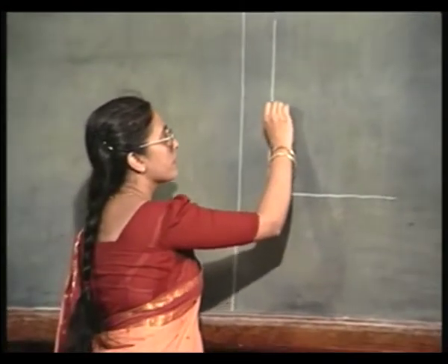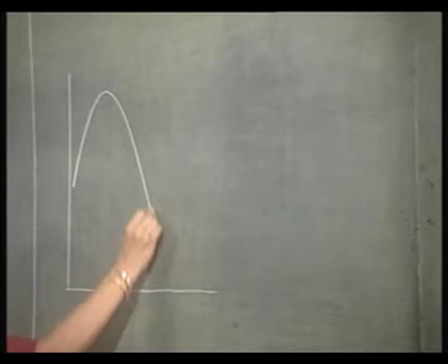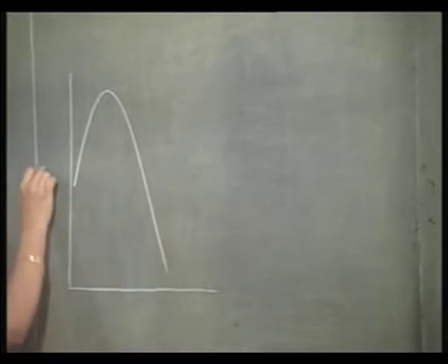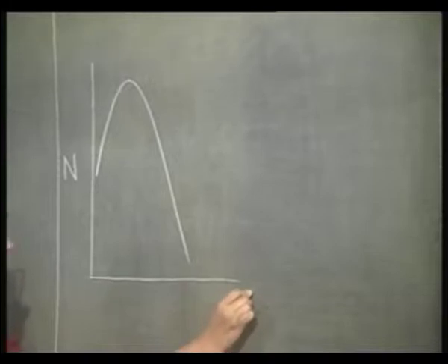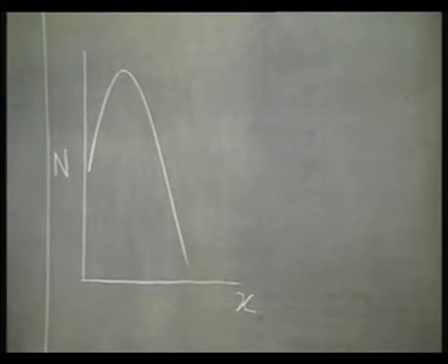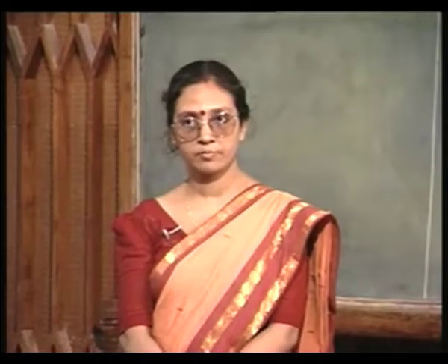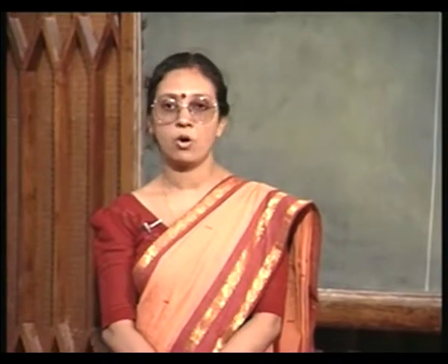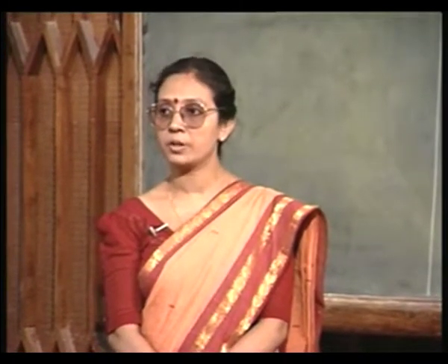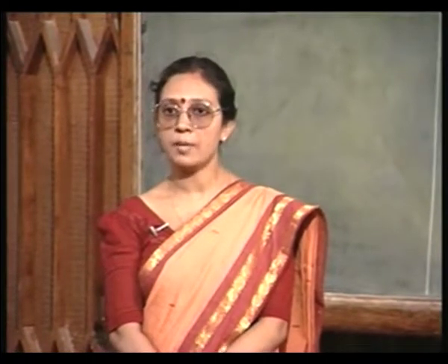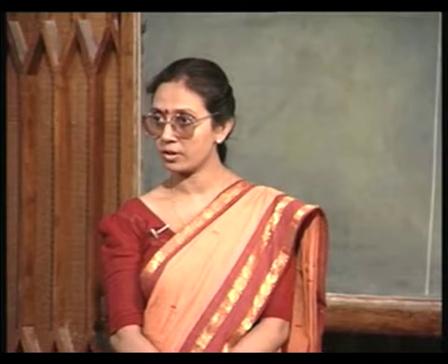So, inside the mask also will have a profile like this, a Gaussian profile with a peak and a standard deviation. Agreed? Now, this masking material has a particular thickness. Whether you have used silicon dioxide or photoresist, you have put a particular layer of some thickness on top of the semiconductor, isn't it?